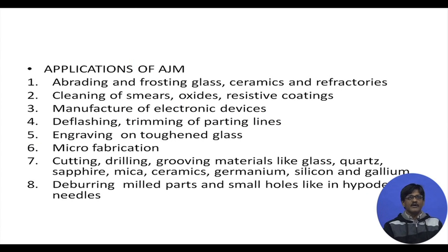Let us discuss some of the applications of AJM. We can have not only cutting, drilling and grooving and other things, but we can also use the abrading action of abrasives to create a frosted glass appearance. So, if we have a glass in which we need a frosted glass appearance, apart from other existing methods, abrasive jet machining is definitely capable of doing it.